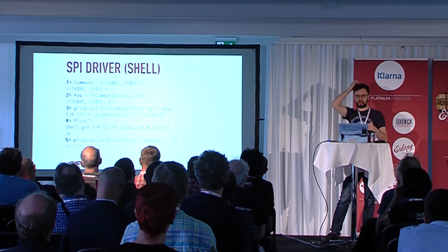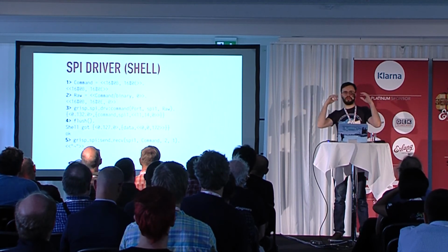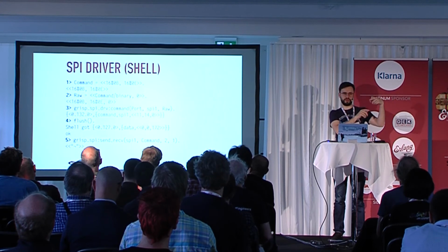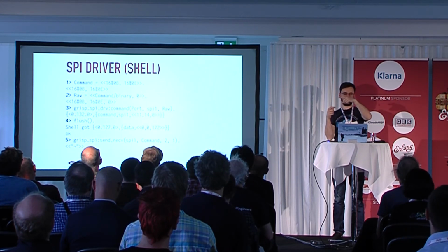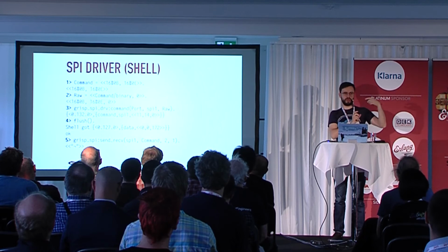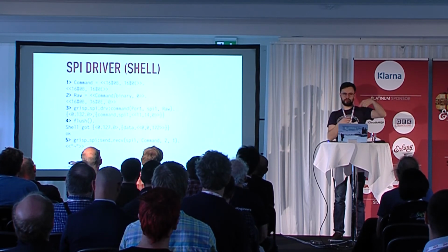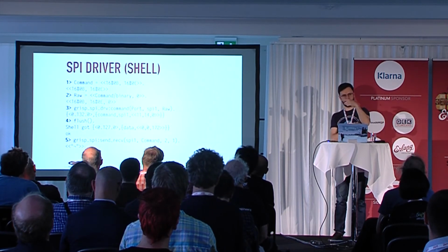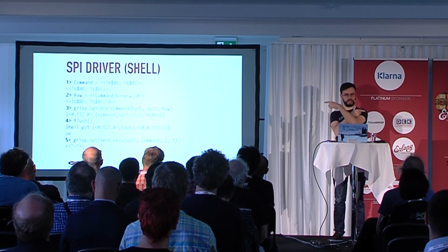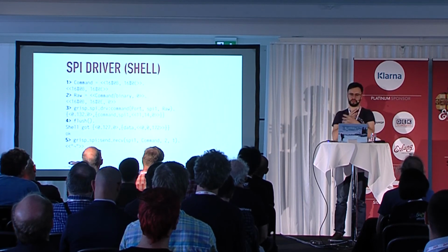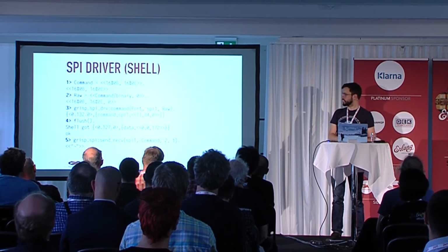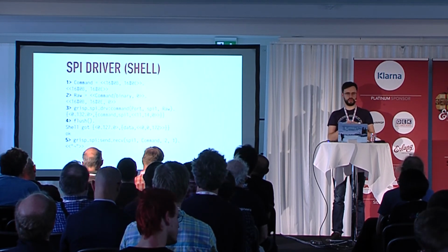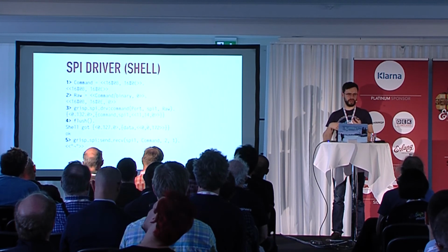So the way SPI works is that it's synchronous. There's one output and one input line. From the master it's one output, and then from the slave it's one output back. And they all go in lockstep with a clock line on the side that dictates the speed. Every time you send 1 byte to the slave, the slave sends 1 byte back to the master. This is what synchronous means here. So we're sending 2 bytes, the command and the register we want to read, and for each of those, we'll get 1 byte back.